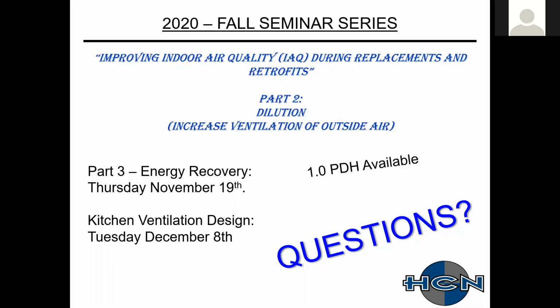I don't know how many people have had familiarity using the AAON RNA horizontal, but it's pretty flexible, and it does give us the opportunity to stick in either final filters or a humidifier at the discharge with a drain pan. There are some limitations. We can't do a humidifier and final filters in that unit, but we can do a humidifier in those specific sizes. So just food for thought.